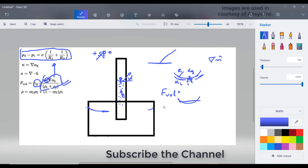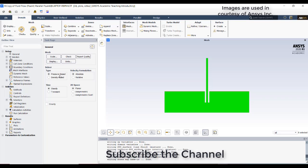So this would be added to the Navier-Stokes equation as F wall. Due to this net effect, the entire liquid column would be pulled up until it is balanced by the self weight, right? So we'll just try to mimic this principle in Ansys Fluent. I have created this with a fine mesh. This is the column, and I'll try to pass water up to this level.